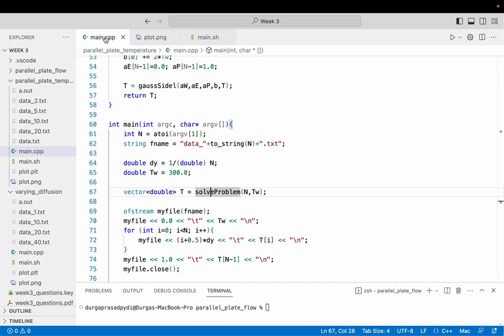What I'm trying to ask is, say that there's a constant temperature here. You say the variation is only 1 degree, but there's a constant heat addition. Eventually, the full flow has to reach the same temperature, right? Am I wrong? You are saying as a function of x, after some distance? No, as a function of time, the same line you take, variation as a function of time. So there is constant heat being added on top or on bottom. It's not a uniform heat flux boundary condition, right? You kept the temperature as constant. It can be heat addition or removal. It can be either of them. The temperature is constant.